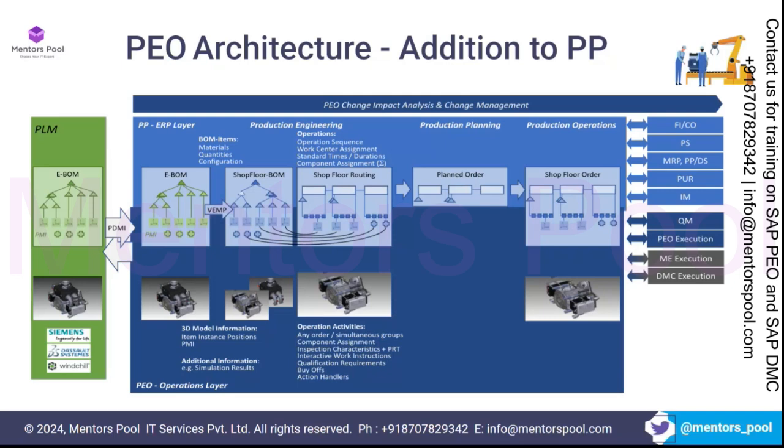Your BOMs should be versionized. So you can use only the production part of it, right? But then, as I will talk about, you need to convert your classical BOMs into PO BOMs, which are the version BOMs. Otherwise, you will never be able to use it in any of these processes that you see here. There are some migration process reports available, but your BOM should always be versionized. Once it's versionized, you can use it directly on the manufacturing side. But whenever there is a change, we need to go with that versioning process for each change. Yes, you need to. All right. Thank you.